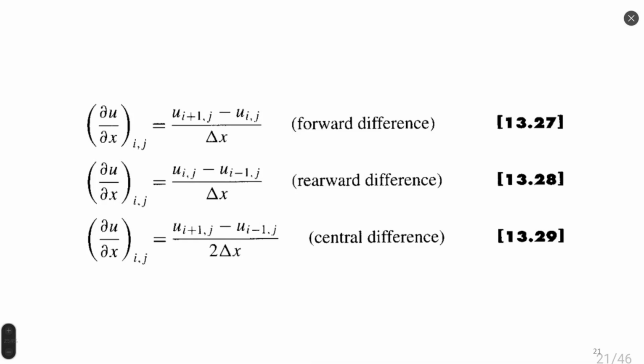But in most cases, explicit solution methods are better because they allow a higher integration time step, much higher. We're talking about tens or hundreds of times faster calculation. So explicit calculation is better. I hope it's explicit calculation. If I'm not wrong, let's look in the book and check.